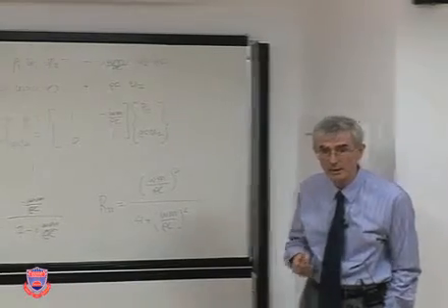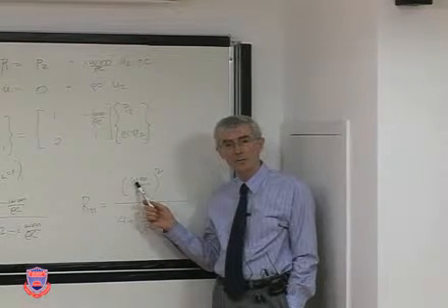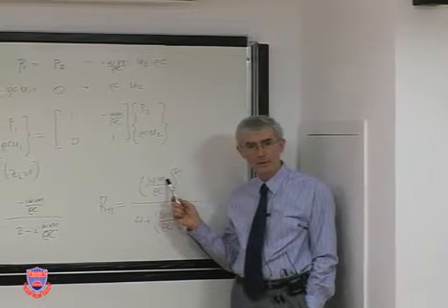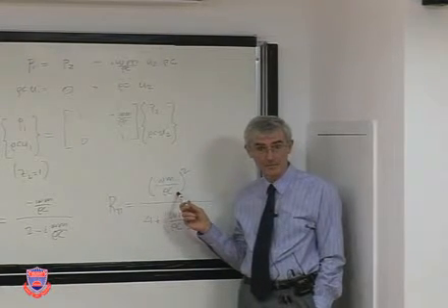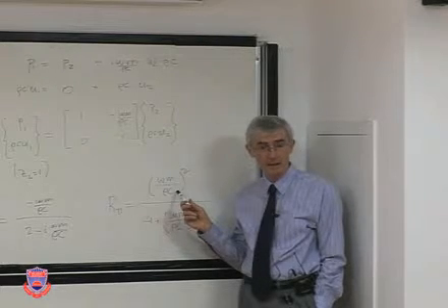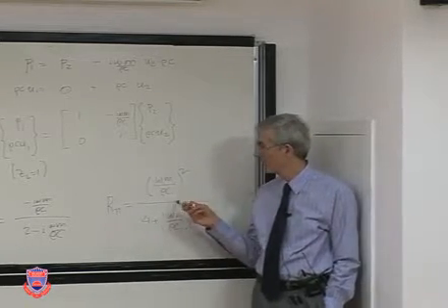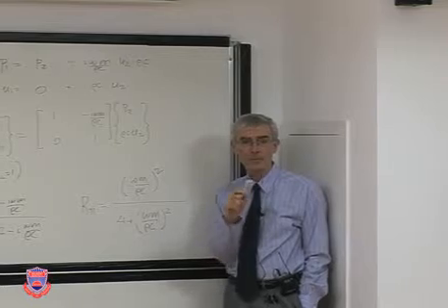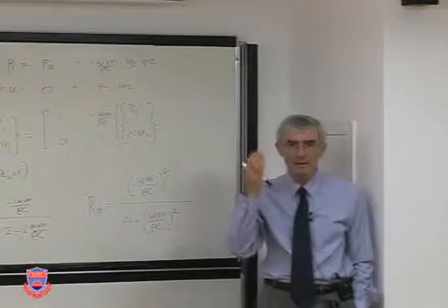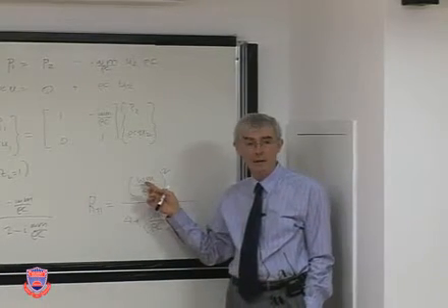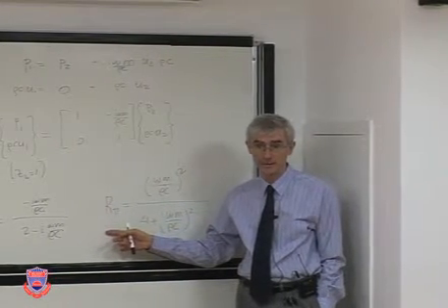This ratio will be very small, depending on the frequency. Now, this is an interesting topic that you bring up, frequency. Look at this. At low frequencies, membrane impedance is very, very small. What does that mean, even in air? If you have very, very low frequencies, an ordinary membrane, what does this mean? Close to zero. Right, and that means at very low frequencies, the membrane will not reflect, sound will go through it.